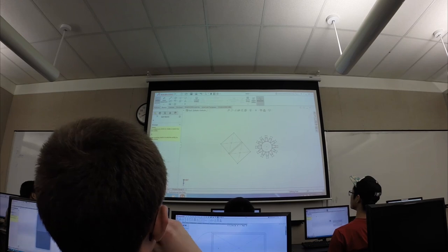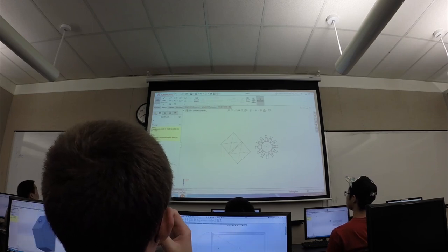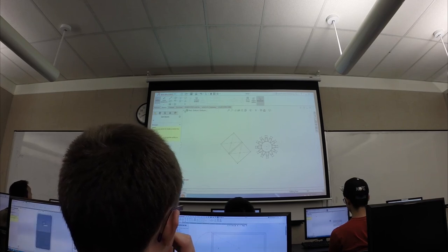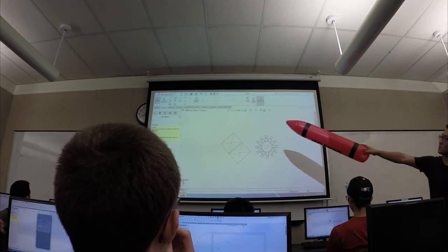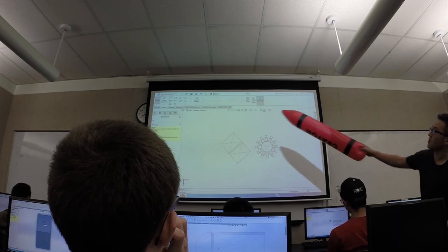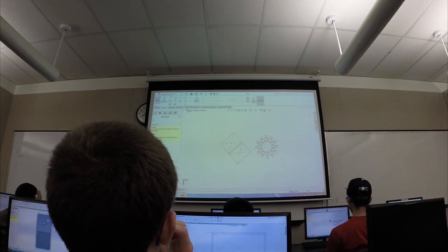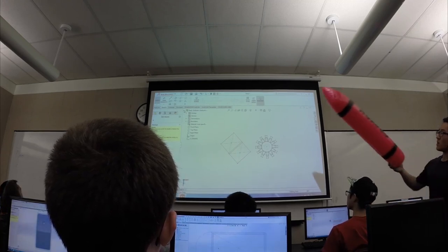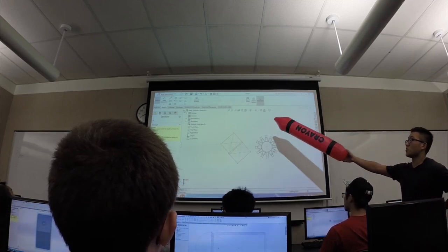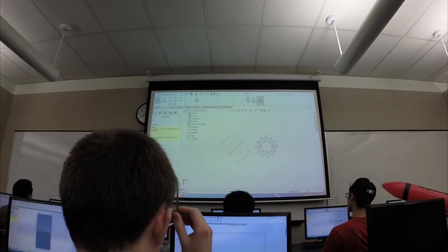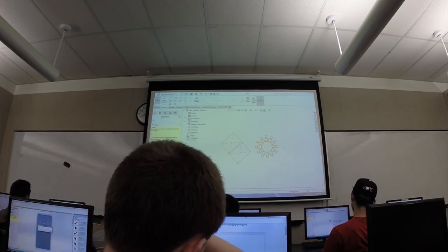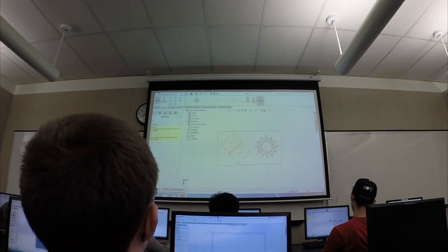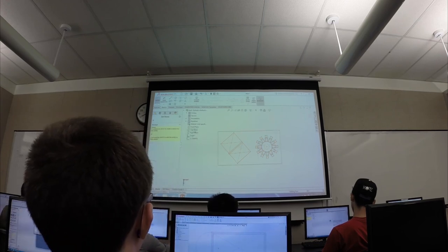Right here, the feature tree moves out on the screen when you're working on a separate sketch like this. There's a little arrow there next to the little assembly icon. Click on that so it drops down the feature tree. Just like that. It'll show you all the things in the feature tree currently. If you wanted to, you could reference the sketch off the first sketch too, but it wouldn't do much because we'd be just drawing on the same plane. We could have done that in the same sketch feature at once.